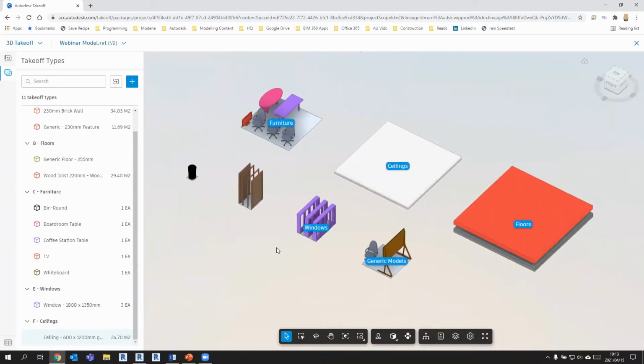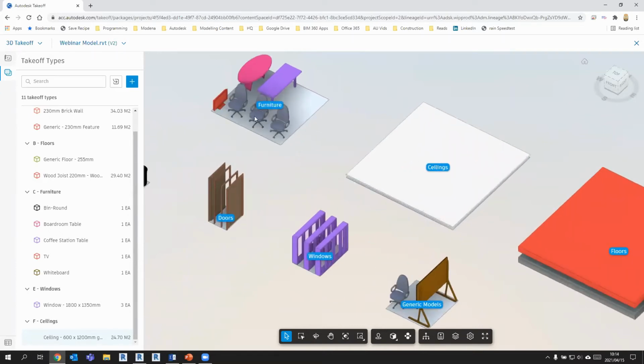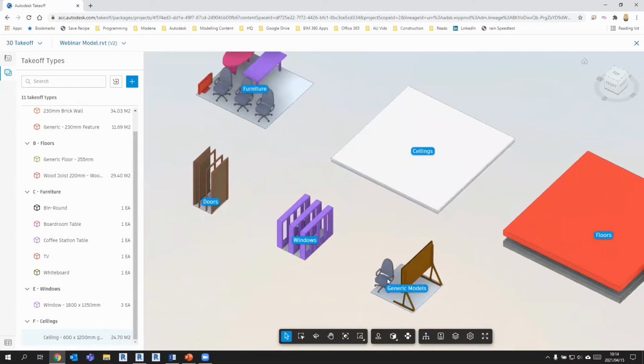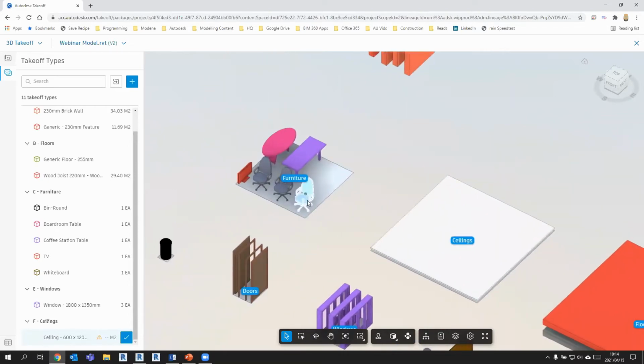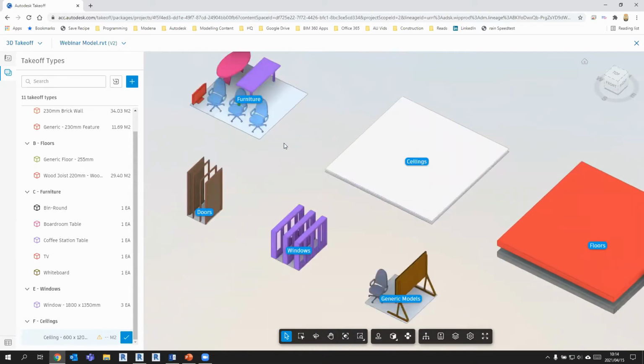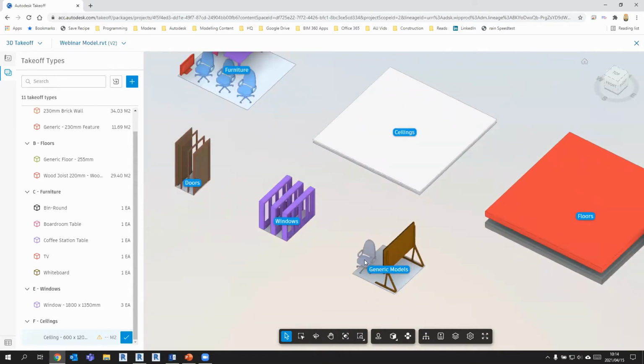So no matter how the guys model inside Revit, it ultimately comes back down to you can see the information and you can grab it. Now I did this on purpose. You can see 3 of my chairs are sitting there and 1 chair is there. It's very likely that you can find that problem working within your environment. So I can go here and say right click, select all chairs, selects those 3. But I can also select this one by just keeping control on my keyboard, and I can do a multi-select.